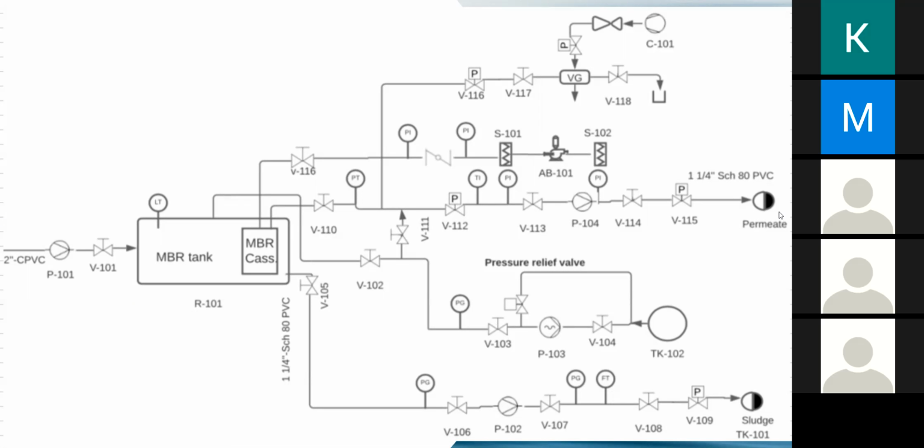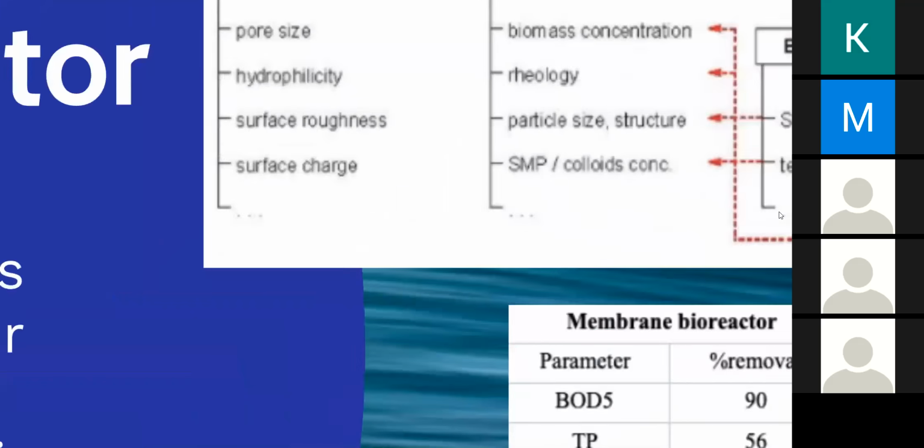Fouling and fouling control are our major considerations when designing an MBR, since membrane fouling is the most serious problem affecting system performance. Air scouring around the membrane and a weekly cleaning using citric acid is very helpful to remove or at least reduce the fouling layer. Next, Jared will talk about the lab's experiments.